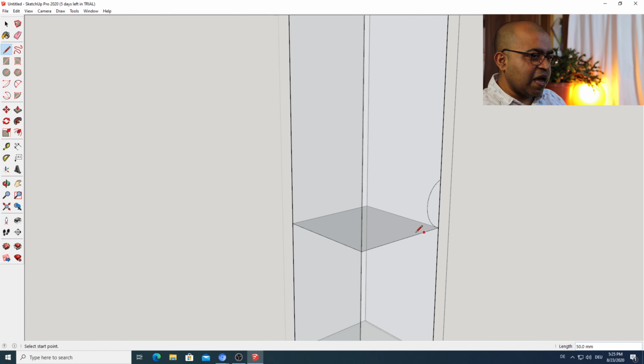So that will complete a plane. So now I have an area which is this semicircular area, and I want this semicircular area to go around using the follow me tool. So to use the follow me tool, you select the area, and these are different line segments. So what I'm doing is, you press the shift button, and because shift toggles, that means when I press the shift button, it's in the addition mode.